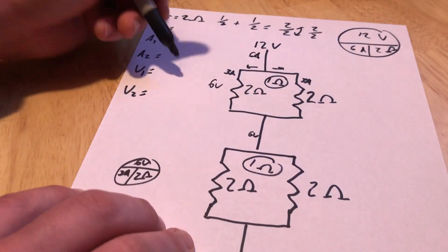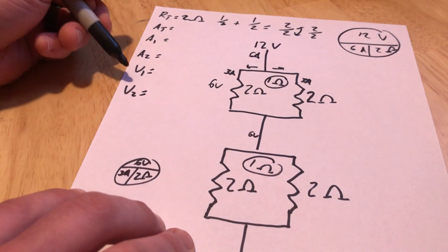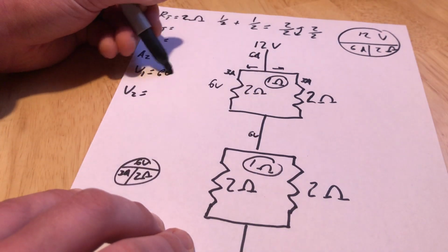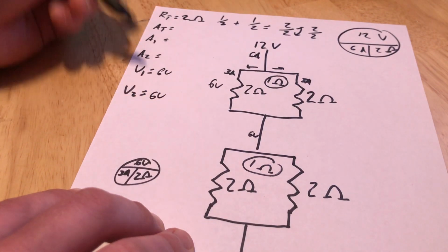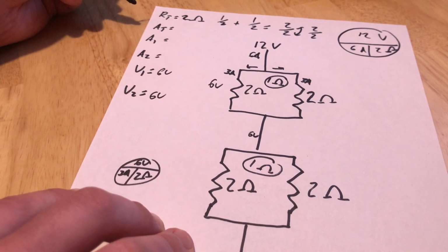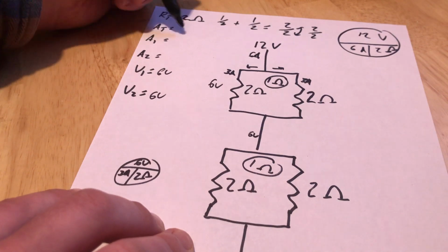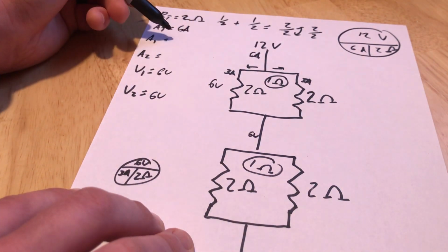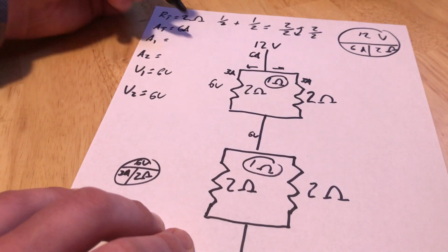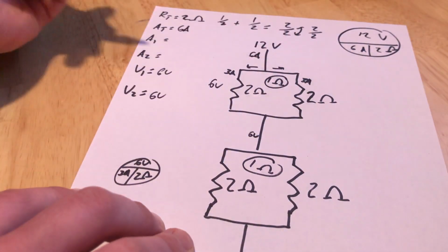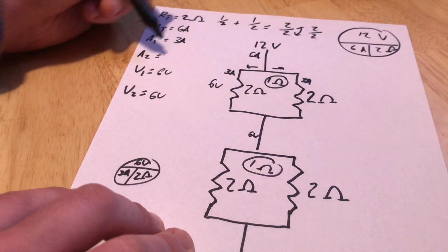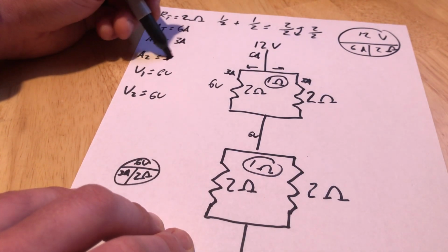So I only put 2 voltages here because really voltage drop 1 is here, voltage drop 2 is here. So 6 volts, 6 volts. And since we figured that out, now all of a sudden we have a pretty good idea of how my amperages were working. We figured out through Ohm's law real quickly about the 6 amps. And then using some of our real thinking cap skills, we came up with 3 amps through each one of the different legs.